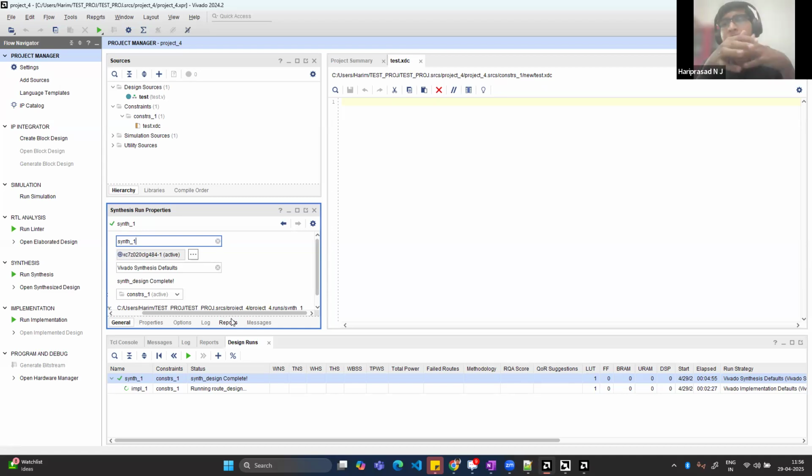So what we did is we went for area compromise. We implemented everything in parallel, and within a short time the whole 3D array can be calculated. That kind of implementation we had done. So it is again a kind of area trade-off. Whenever you compromise area, you can achieve a lot of high speed. But when you try to reduce the area, you have a limited lookup table. So with the limited resources, you have to keep reusing them again and again. So those compromises will start happening. So it's all interrelated.